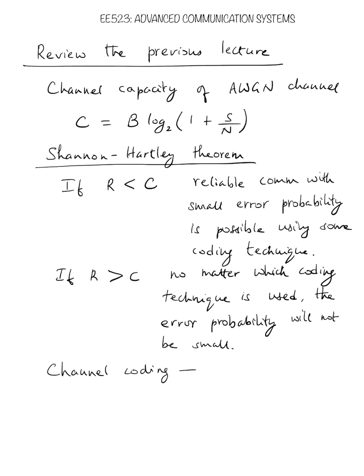And in this, the first type of channel coding technique that we saw was a very basic one, which is called the parity code. We discussed what a parity code is in the previous lecture. In a parity code, we have some bits called the information bits, and to the information bits we add a single parity bit. After adding the parity bit by following some rule, we combine the information bits and the parity bit, and together that is called a code word.